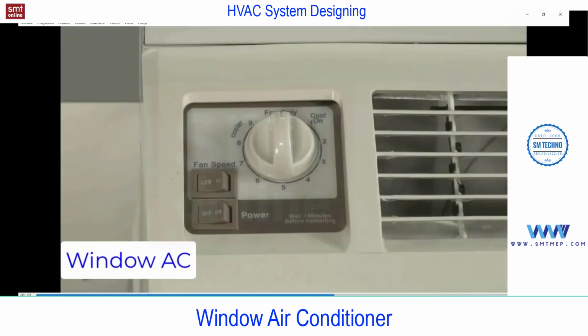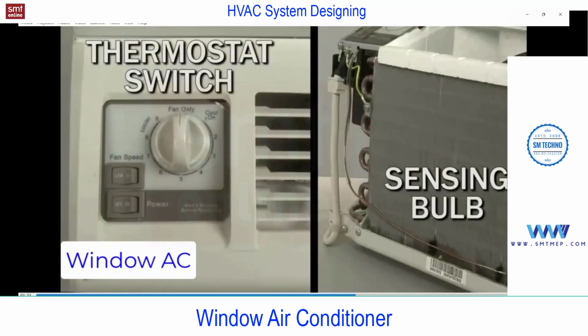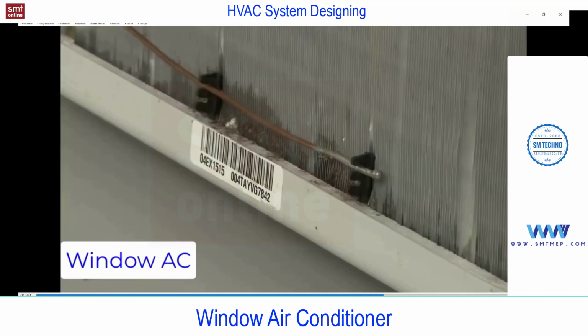The air temperature is regulated by the thermostat control. Depending on the model, the control may be a thermostat switch and sensing bulb assembly, or an electronic control board that works with a sensor. The sensing bulb or electronic sensor, you see, this is important. The sensing bulb you will find when you remove the front panel, before the evaporator. This is related to the evaporator side.